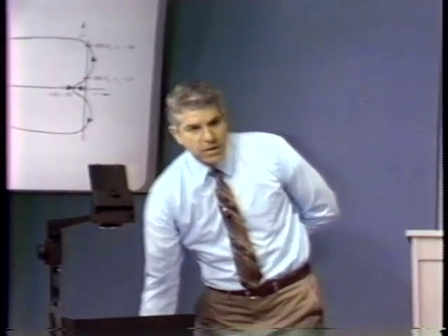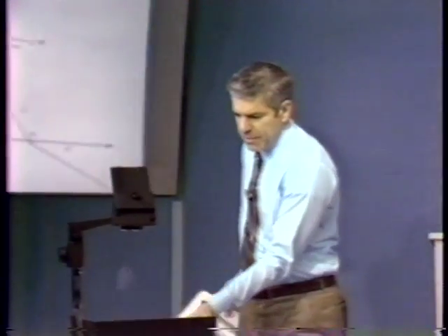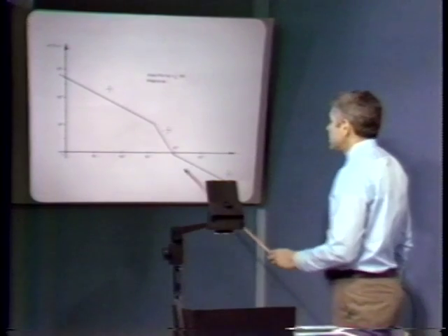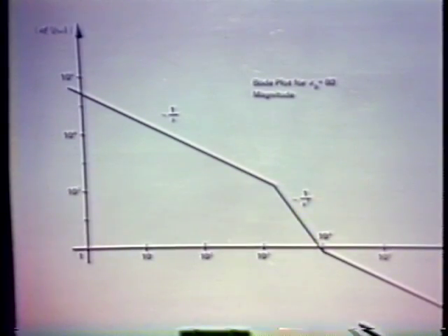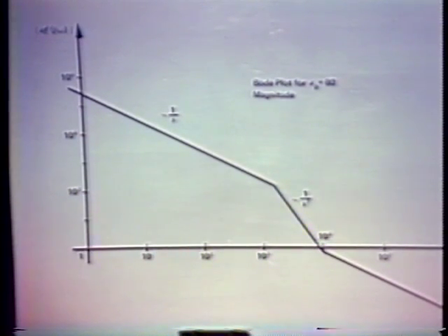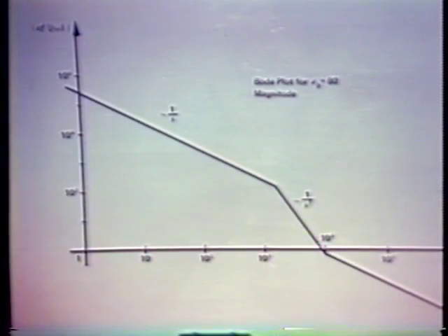We can again look at this in all the other ways we've seen. Here's the magnitude portion of a Bode plot. We find that if we choose a value of A0 of 80, very nearly the maximum value we can get with our 100K potentiometer, and take care of the rounding in here, the crossover occurs at just about 10 to the 4th radians per second.